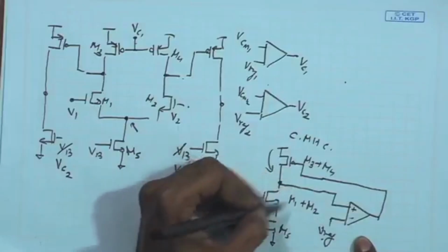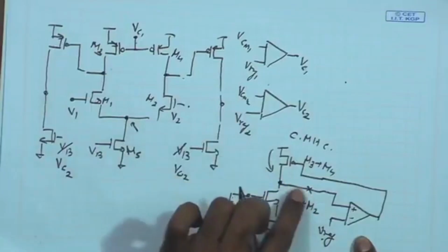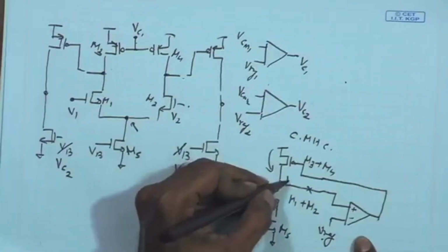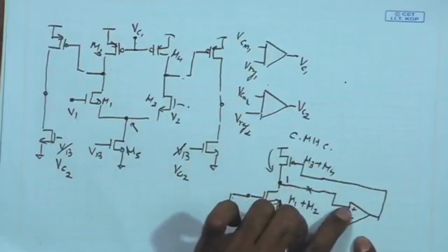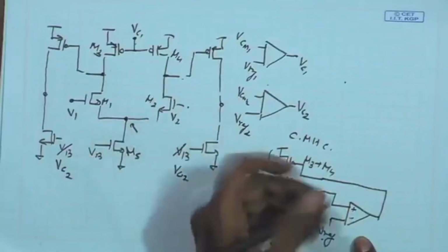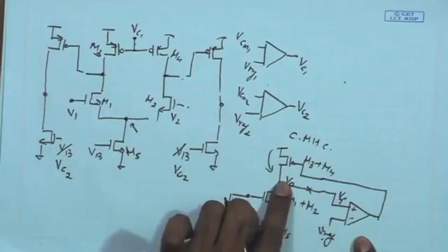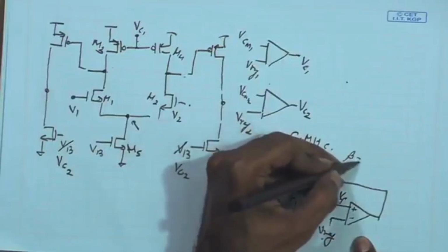And if I have to open the loop, I can break the loop over here at this point, and what we can see is that the output voltage over here is being applied as it is to the feedback terminal. As a result, what we can say is the Vf, or the feedback signal, is equal to Vo. So, basically the feedback factor is 1 essentially.